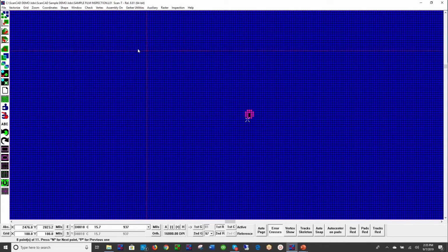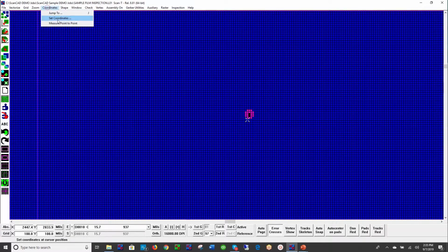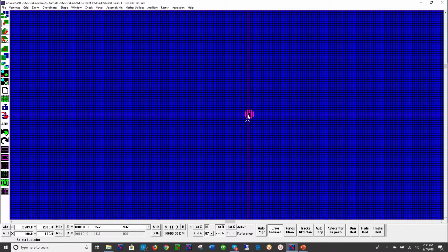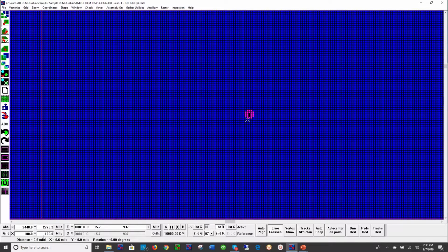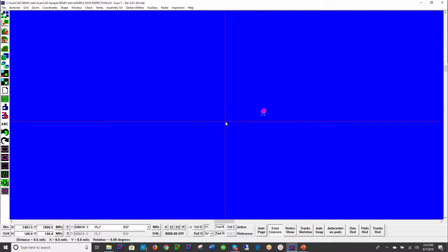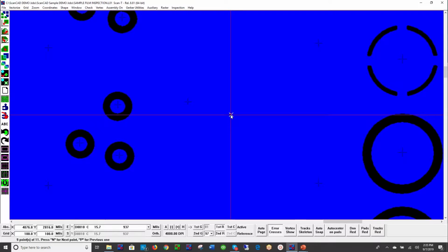In fact, I'll just measure this pinhole. Remember, we have measurement capability. I can measure this pinhole, and we can see this pinhole is 0.6 mils, approximately 13 micron. This is a 13 micron pinhole in the board, okay?